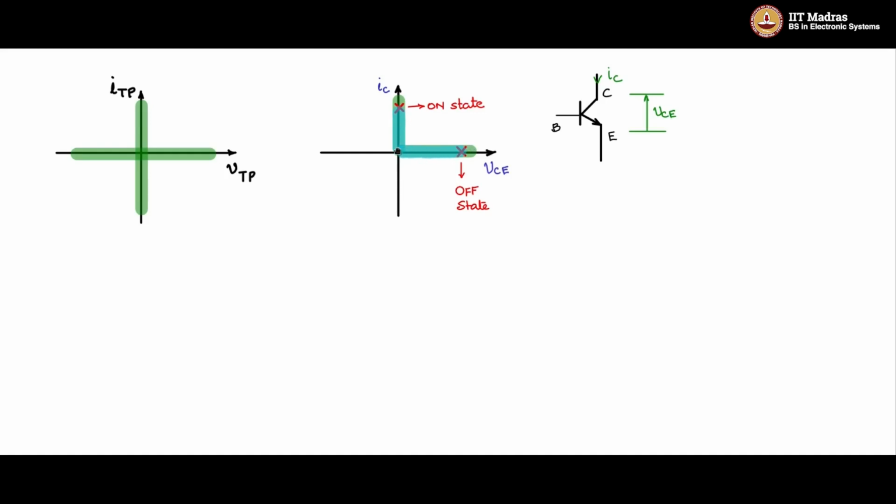And then once 0 voltage is reached, in all this portion of the route, voltage is 0. So in transiting from the off state to the on state, you do not lose any power. Likewise, while coming back, you also do not lose power if you are using this route. So in this route, you have 0 switching losses. Which basically means that if I am switching with 0 voltage and 0 current, then you have zero switching losses.